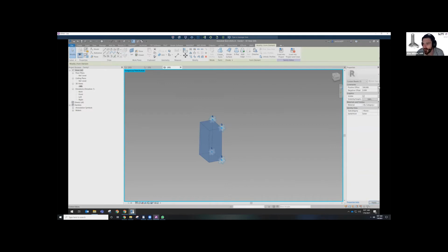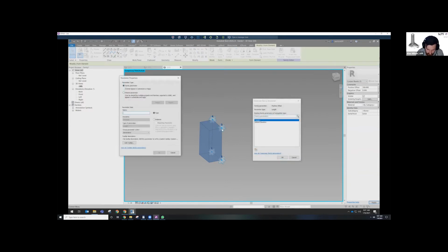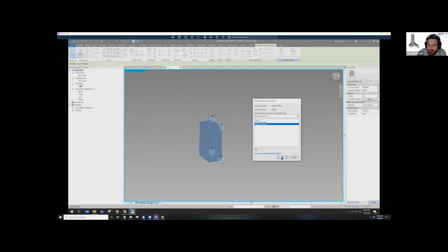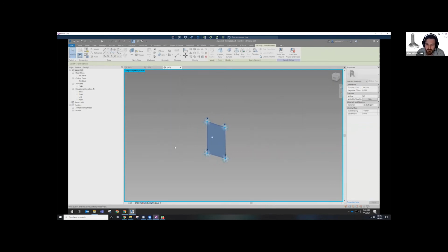You can also assign parameters. So if I want to give it a thickness here, I can just create a new parameter. Similar to the numbering of the panels, it's important to have a convention. Personally, I like all caps for the thing it's controlling, and then underscore the description. So you can create parameters here.